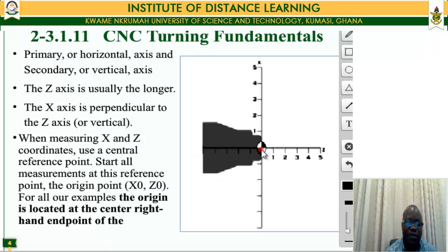Then you have the absolute zero position set at the geometric center of that particular part. So the zero position will be at where I am displaying the cursor. And then you will start programming from that center toward the workpiece to actually ensure the material removal and all that. So that is why we position the zero or the path reference zero on the CNC lathe machine.